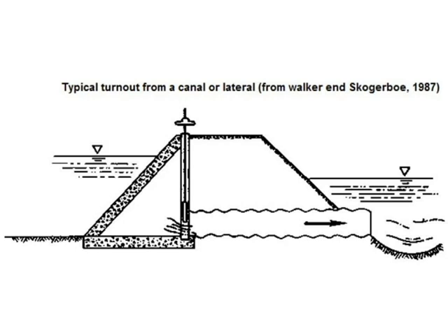The water level required varies with the type of takeout structures, but the head should be at least 10 centimeters, which is about 4 inches.